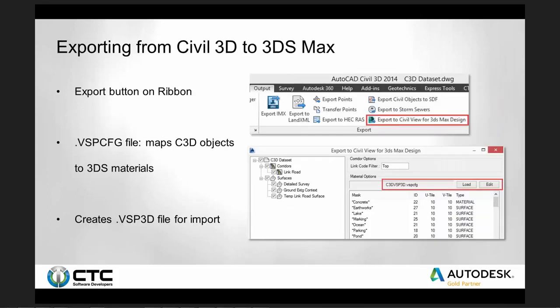So where we're going to start today is by exporting from an existing Civil 3D model, and it's going to be a kind of transportation-focused presentation today. One thing you need to know in Civil 3D is the export to Civil View for 3ds Max design. That's on the Output tab of Civil 3D. What this does is it exports a file that can be imported into 3ds Max. The second image you see there is the export dialog box.